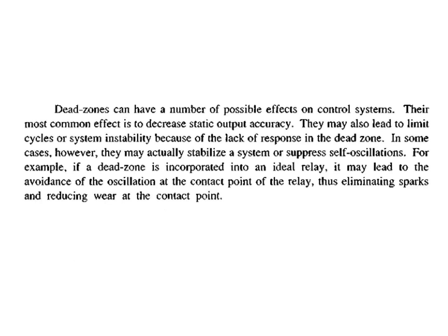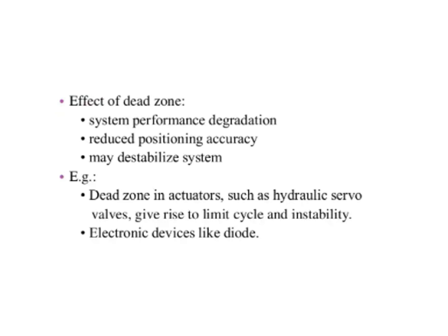Okay, a dead zone has a number of possible effects on the control system. It decreases accuracy, and it leads to instability. So it degrades the system performance, reduces the accuracy and may destabilize the system. One example is an electronic device like a diode. The diode will exhibit the dead zone. This is one of the nonlinear elements.